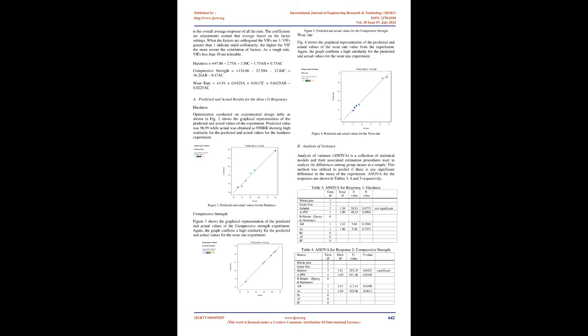Then, desired amounts of epoxy resin were poured into a separate container and the required quantity of hardener was added to form the matrix. The quantity of epoxy resin was added in the ratio of 2:1. The mixture was thoroughly stirred for about 5 minutes to obtain uniform mixture. Thereafter, the matrix mixture was poured onto the powdered friction material mixture and stirred further to obtain paste-like homogeneous mixture. The formed paste was poured into mold cavities that already had powdered talc applied for ease of component removal.